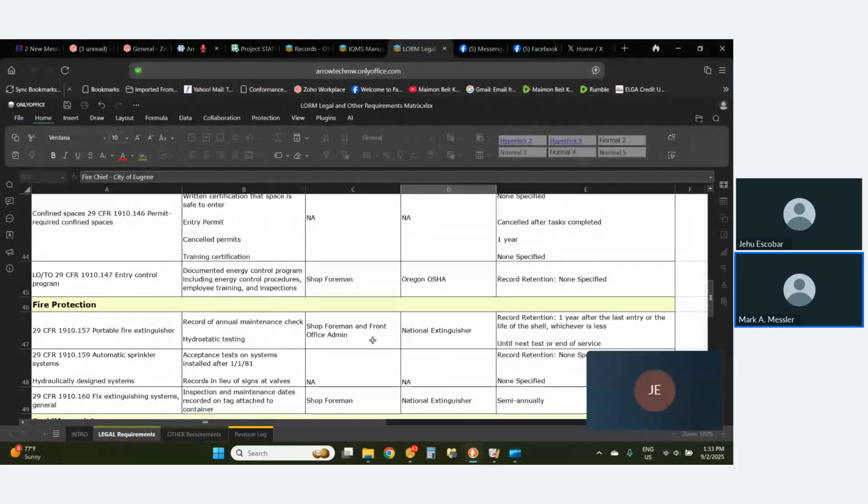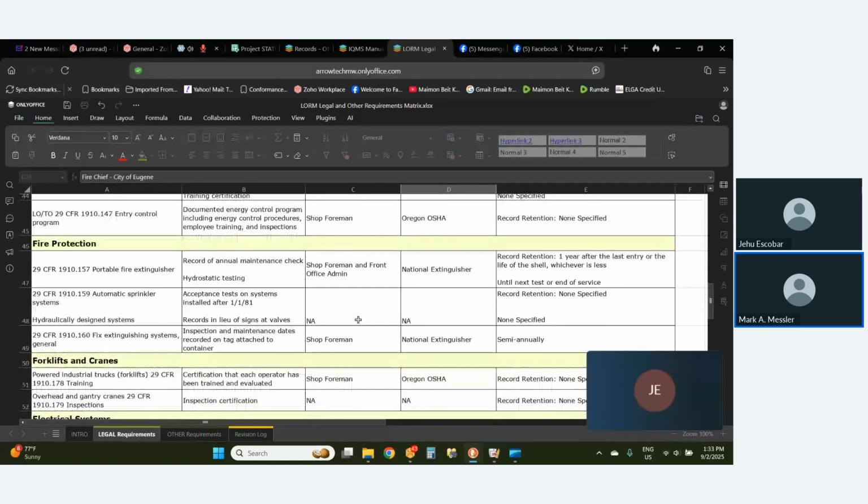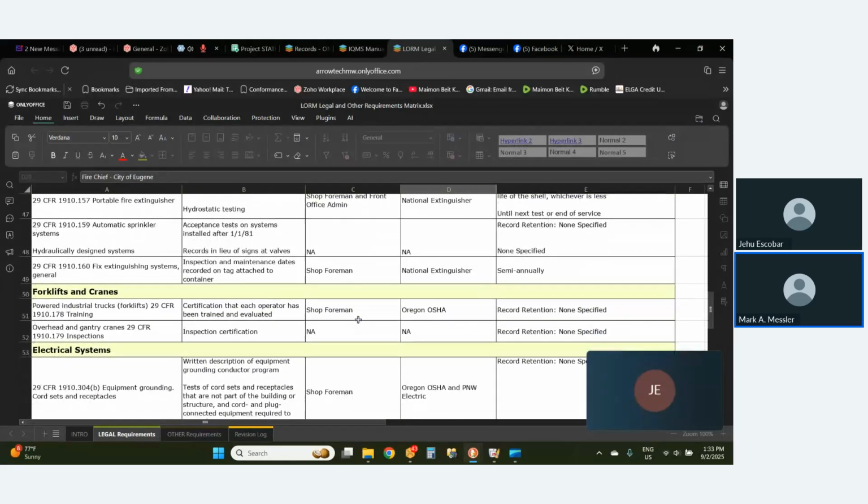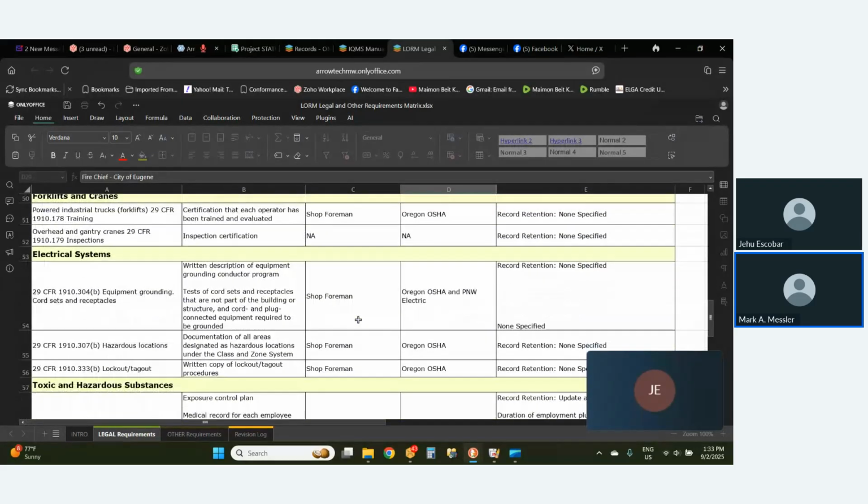You have to wear a mask and a respirator and everything in there because the stuff that's on the steel actually sucks all the oxygen out of the air. Oh wow. Yeah, we actually had a guy get killed at General Motors going into one of those without his respirator. Jeez.